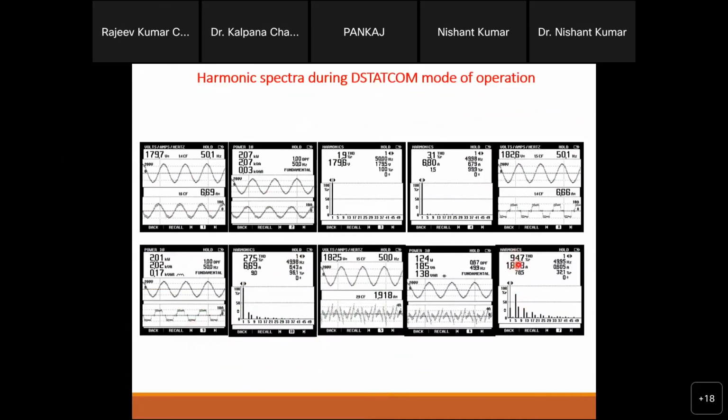And in the night time, for the VSC behavior, you will see 94.7% THD on the VSC, because the VSC is only generating nonlinear currents. These are the current waveforms from the converters, right? But this side, the load is taking 27.5% THD, a balanced load day and night, and then the grid current is smooth, at 3.1%. Since we have this StatCom behavior, only then is this 3.1.